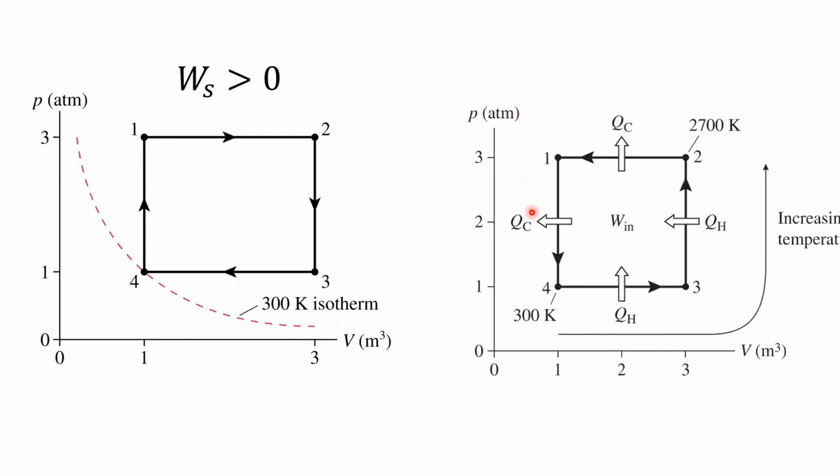But remember, there's going to be an isotherm through this bottom left corner. There's another isotherm through the top right corner. And for this problem, I think we're going to find that there's a single isotherm cutting through both of these points. So you have to think about the second law of thermodynamics and the direction of heat flow.